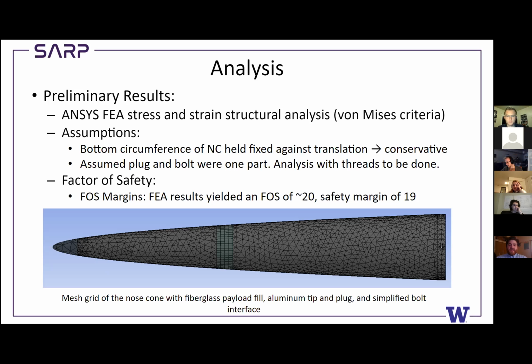We also don't know the conditions at apogee, so we don't know which way the nose cone will be moving. So we just put a fixed support at the base of the nose cone to simulate the force of the nose cone onto the tip.